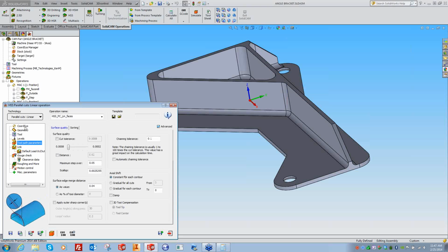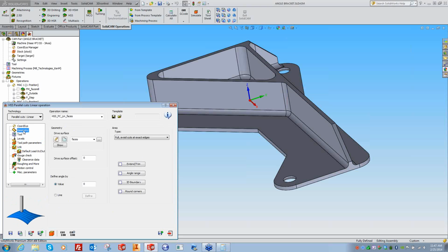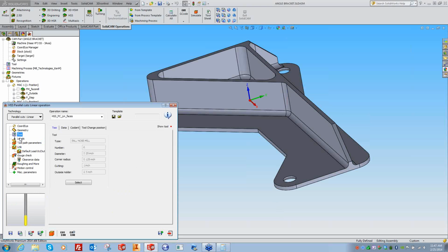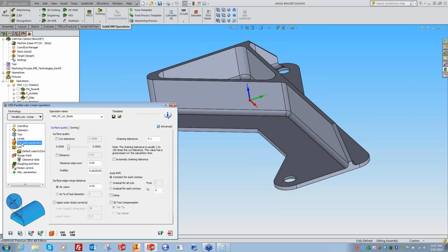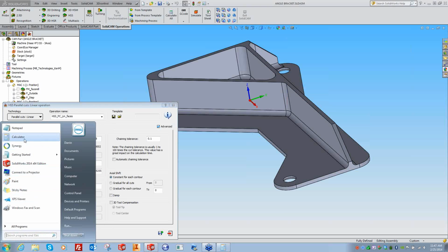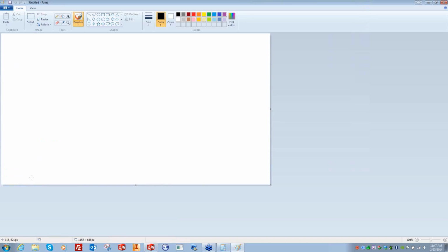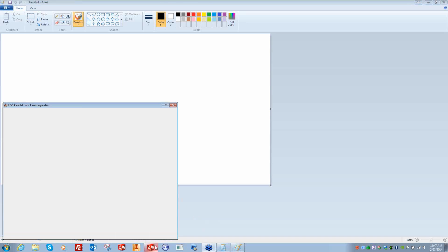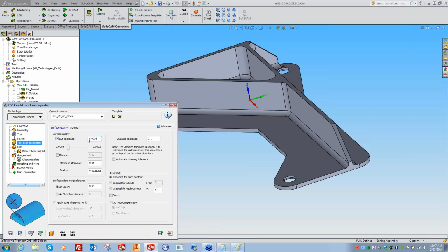So in Toolpath Parameters, so here we set what? We grabbed the faces, we grabbed a tool, we didn't even look at levels really, and Toolpath Parameters. Now, the way Toolpath Parameters works, like this cut tolerance, let me turn that on. I'm going to show you exactly how surfaces are cut, and I'm talking about this particular cut tolerance right here. This is a surface quality.